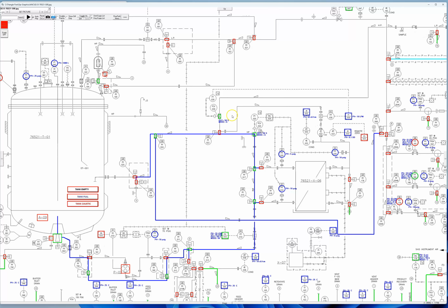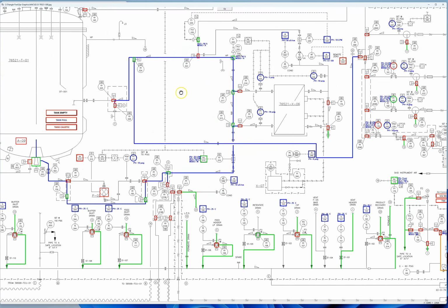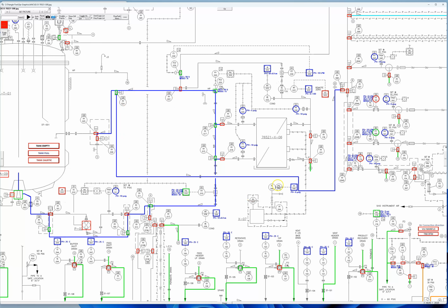What you can also do, to give an idea of how long it takes to generate all this, which includes the ability to generate flow paths: it took about a week. But once you digitize a P&ID, you can do a lot, from IO generation to full path generation for the process engineer, which can then be passed on to Delta V, and you can use it to locate where it is in Delta V, and actually vice versa.